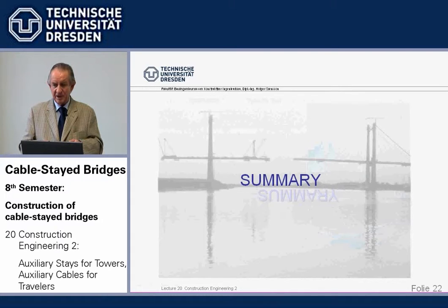And we mentioned, depending on the span to depth ratio of the cantilever, we can sometimes, if we have a very deep beam with small cantilever lengths, be able to lift very heavy elements without any auxiliary tiebacks.